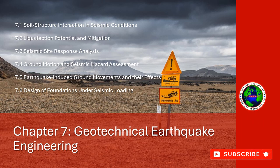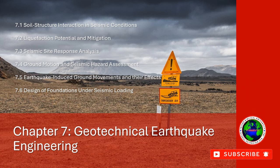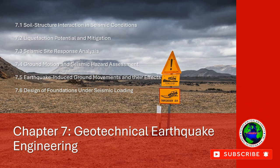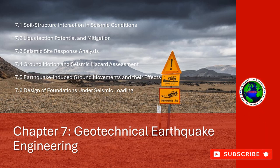3. Seismic damping systems. Damping devices. Tuned mass dampers, viscous dampers, or friction dampers can be installed in buildings to absorb seismic energy and reduce vibrations, improving the structure's seismic performance. Viscoelastic materials. The use of viscoelastic materials in the foundation or structure can provide damping and reduce the impact of soil-structure interaction.